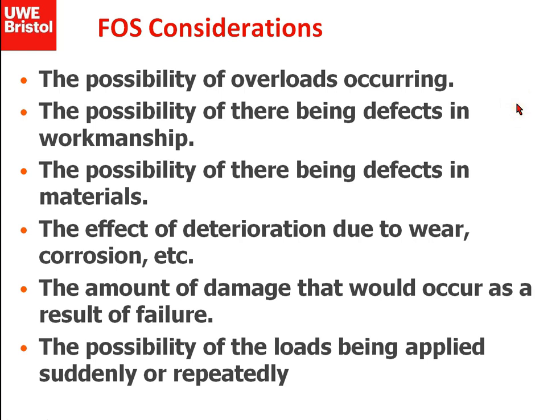The reason why you want a reasonably high factor of safety is because although you tell the company you've built the bridge for, yeah, this bridge should take 5 cars on it, they might decide, okay, let's put another car in it and get some more money. So the operator might not load your structure how you've designed it for.